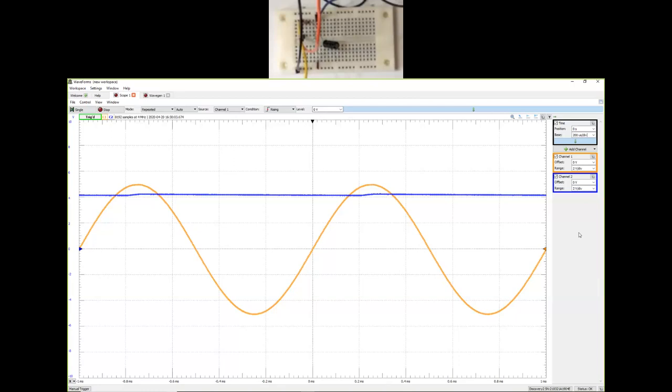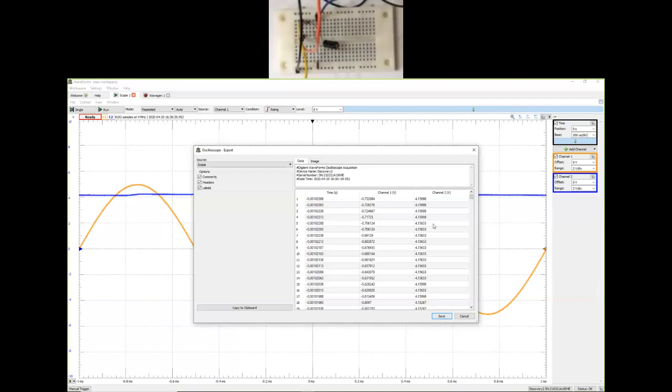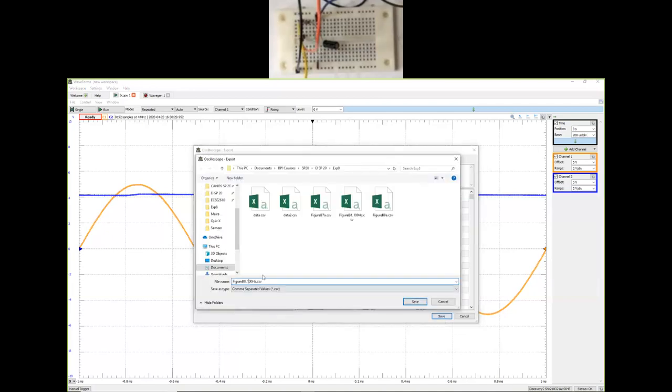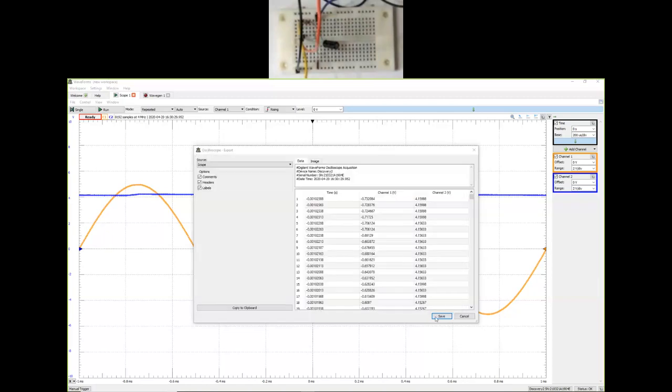So this is probably going to be a better comparison as far as the impact of input frequency on ripple voltage is concerned. So clearly, leaving everything else the same, if you increase the wavegen frequency, your ripple voltage goes down, as is demonstrated using waveforms here. So I'm also going to export this one as a CSV for you to use. This one is going to be 1K instead of 100 Hertz, and it corresponds to figure B8 itself. So save that, sure.